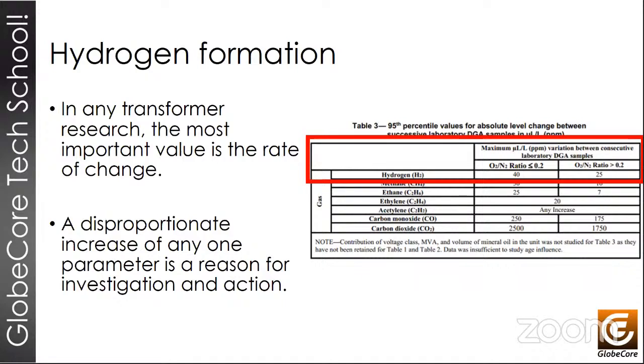It's important to note that these changes are not directly related to the previous tables, because if the changes presented in this table take place regardless of the status based on oil levels, the transformer will be determined as a status 3 transformer.